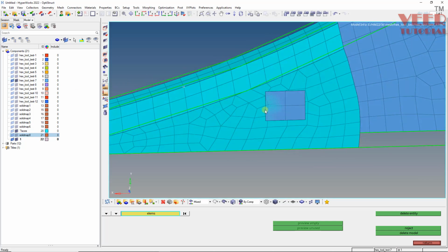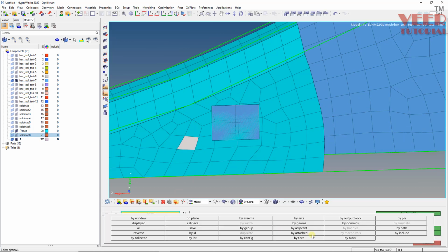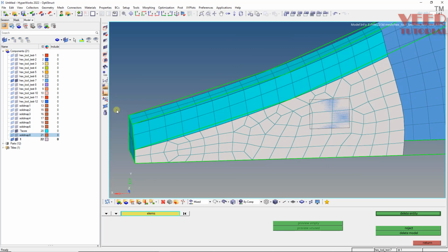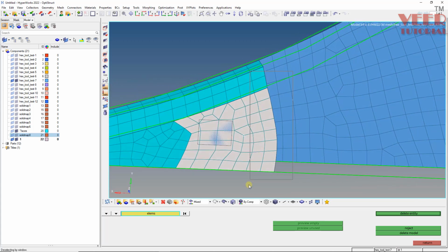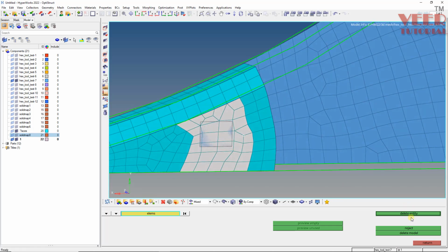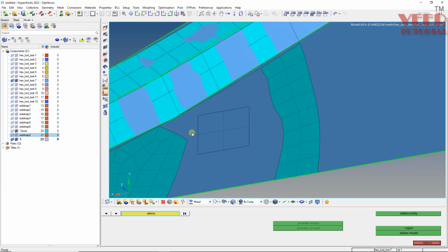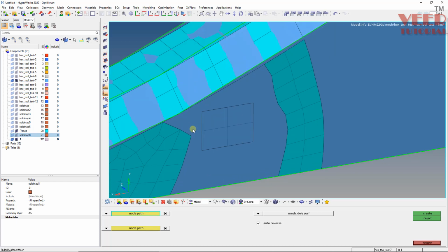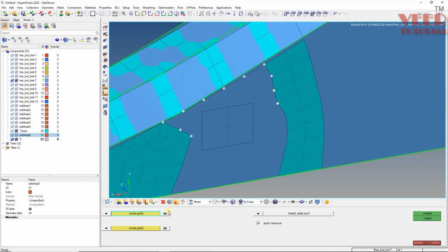also the mesh. I need this projection onto this mesh, so press F2 and delete some element by face, not delete here, so I will leave this, and similarly I will leave this and delete, and solid view. So I will make a ruled mesh here, so press R and make a ruled mesh like this, and okay, here up to here, node path like this.